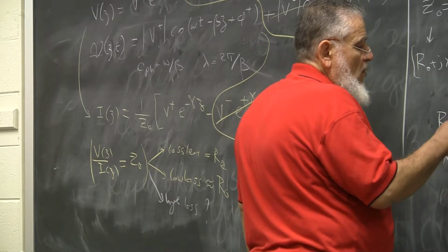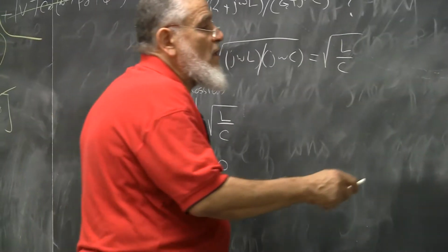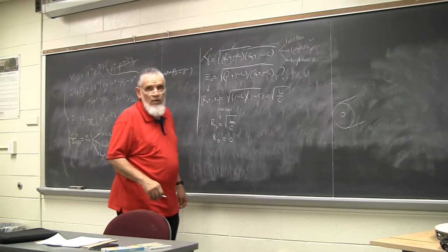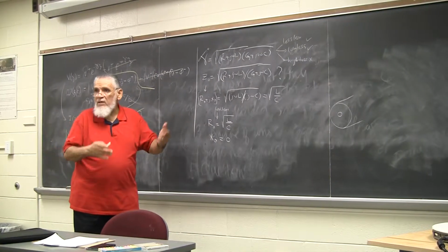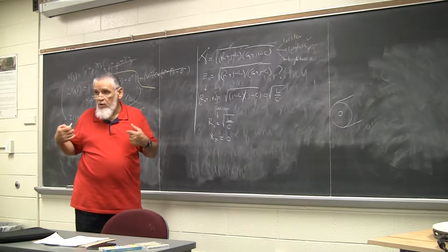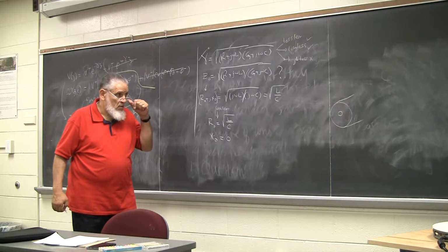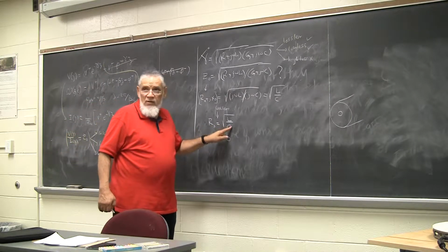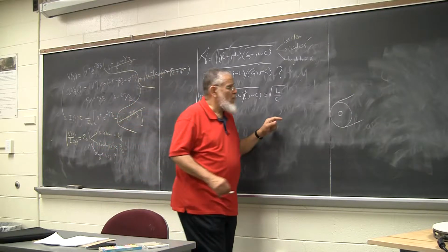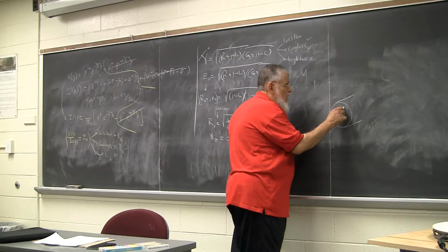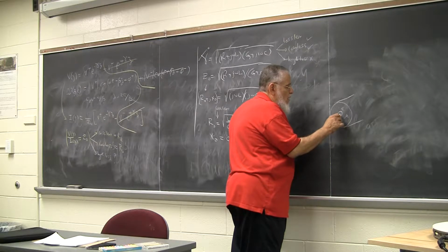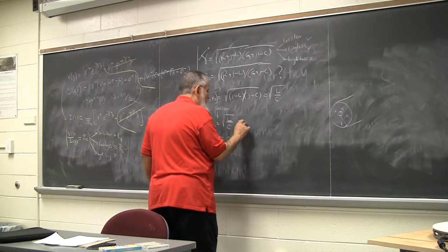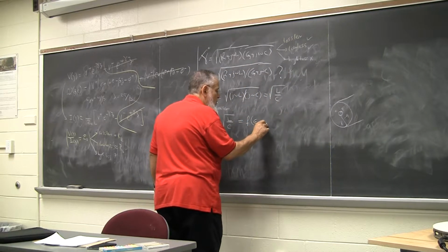If you look at this ratio and go to a coaxial line, for example, and derive the expressions of R, L, C, and G based on the physical dimensions, which supposedly you have done in 3106 or 3105, the capacitance and the inductance are parameters of the dielectric constant epsilon, the mu of the media, and the radii a and b. All right? So this one here will be a function of epsilon, mu, a, and b.